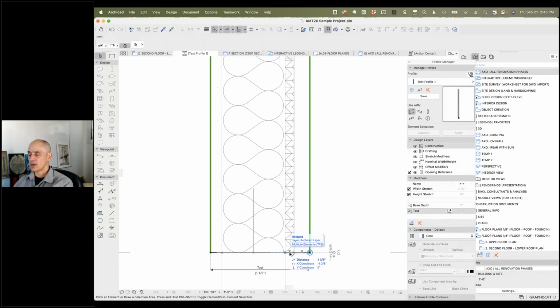So I found that for this type of common situation with walls, doing it from a node point works better. In the actual ones that I'm using for the walls in that sample project, I have a framing, and I'm measuring it from the top of the framing as a corner point, and then it's saying, hey, it's going down to cover that. That's 1.5 inches, and or further, but it's measuring from that point. Anyway, you'll get two arrows if you go to two edges. You'll get a single arrow if you're going from a node point. Okay.